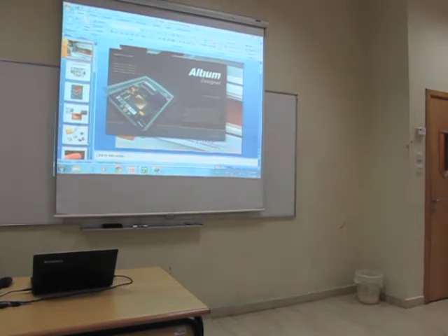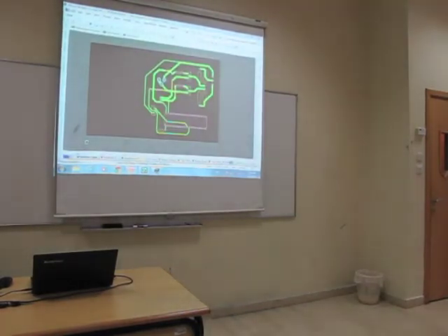Which one is better, using a chemical to dissolve the copper? Actually, this is a very good way just for prototypes. In industry, when you want to do mass production, it is very expensive. This one is good even for mass production, but only if the board is not very complicated. As boards become more complicated and finer, tracks become thinner and thinner and components become smaller and smaller.